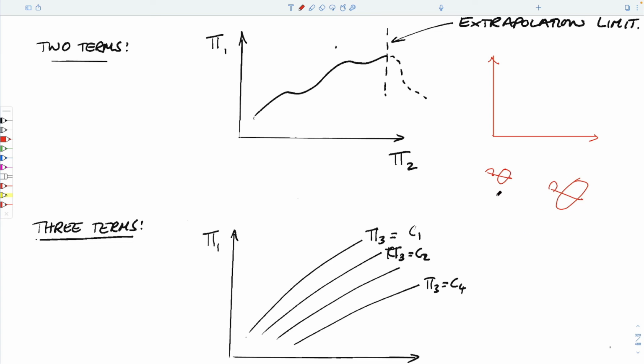What we did was we said that the geometries of these two should scale exactly, geometric similitude. We said that the Reynolds numbers should scale. So the Reynolds number for the model should equal the Reynolds number for the prototype.